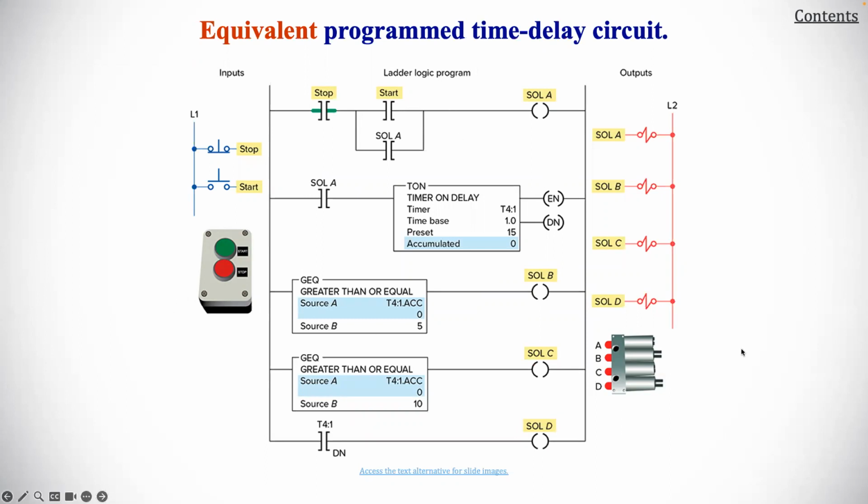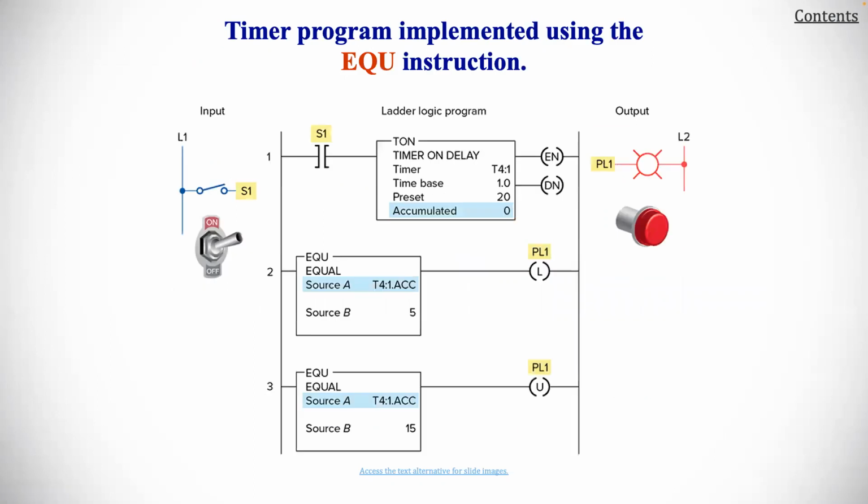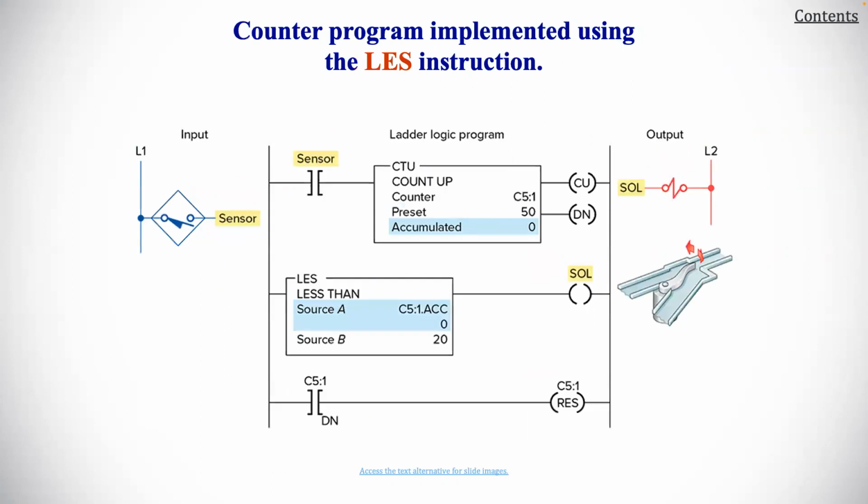You can pause the video and look over this, but we're seeing these various implementations with the PLC approach. Here's a timer program implementation using the EQU instruction. This might be an example as you do some practice programming to see how that looks. Here's a counter program that is implemented using the LES instruction.